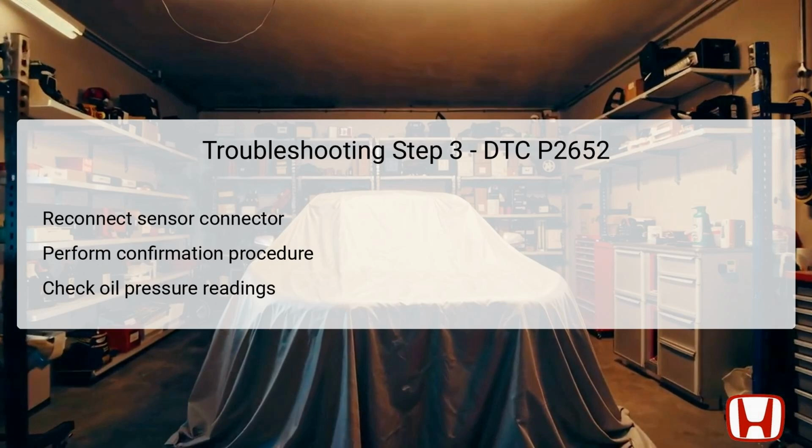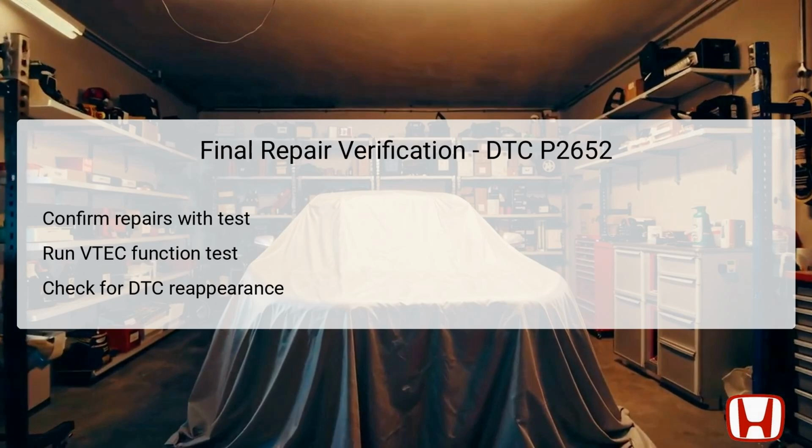The objective is to check if the oil pressure is below 49 kilopascal, indicating normal conditions. If the pressure levels are within the specified range, this reveals that the sensor may have a fault. If they exceed this limit, it suggests further examination is needed for the control valve and related components, thereby guiding subsequent troubleshooting efforts. Once repairs are completed, it is crucial to conduct a final verification to ensure that the initial issue indicated by DTC P2652 has been resolved effectively.